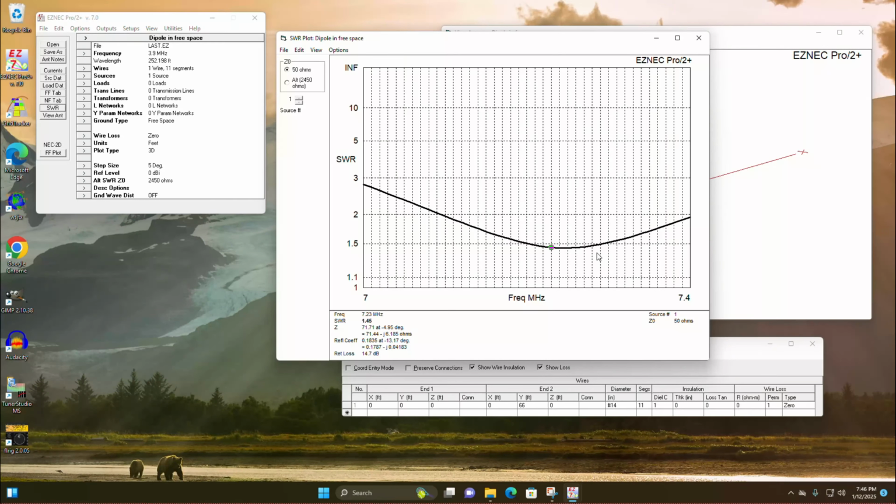you can see it's very similar to what we had before because we were up 38 feet, which is pretty good for a 40 meter antenna. But you can see we're at right about 70 ohms, 71.71 ohms, which is typical of a straight dipole. Straight dipoles usually end up about 73-ish ohms is where you would expect to see one of those.